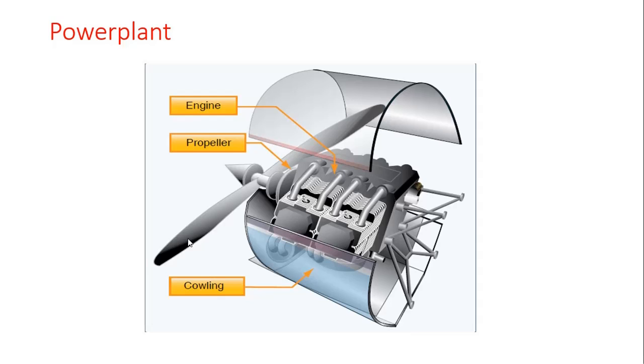A propeller is a rotating airfoil that produces thrust through aerodynamic action. A high pressure area is formed at the back of the propeller's airfoil and a low pressure is produced at the face of the propeller. Similarly, the lift is generated by an airfoil, which is used as a lifting surface or wing. This pressure differential develops thrust from the propeller, which in turn pulls the airplane forward.